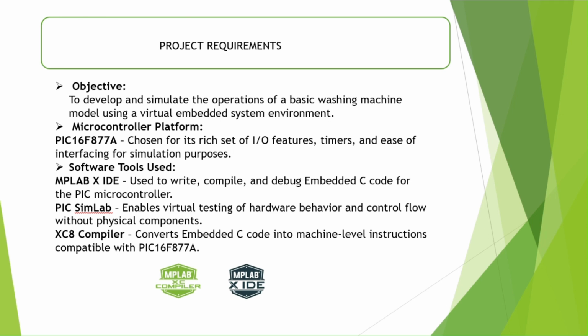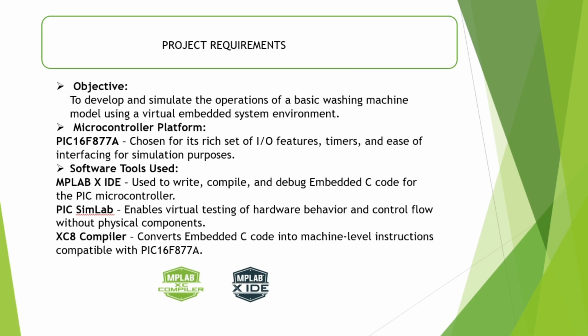This choice was deliberate owing to its robust set of input-output features and versatile timers. For software tools, we used MPLab X IDE to write, compile, and debug our embedded C code, and Picsimlab for visual testing of hardware behavior. The XC8 compiler was used to convert our embedded C code into machine-level instructions.